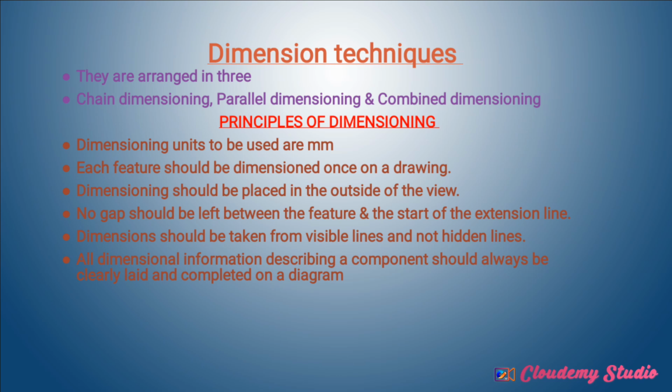So I discovered that most of you waste your time to draw a title block, which you can do in approximately 5 minutes. Because if you take 30 minutes to draw a title block, which only gives you 4 marks, you forget that the entire paper has 80 marks in it. So it's better to do it faster. Make sure that you use the least time possible to draw the title block, then draw the borderline, then start performing the actual drawing, because that is where the actual marks are.